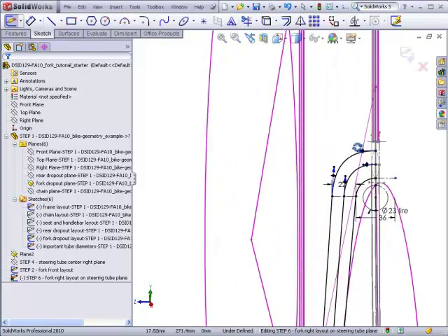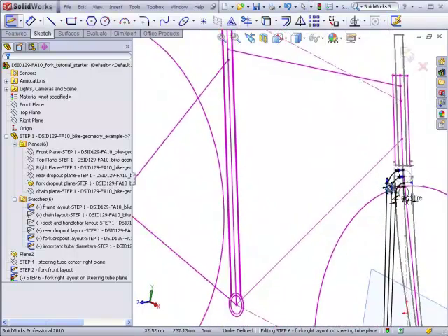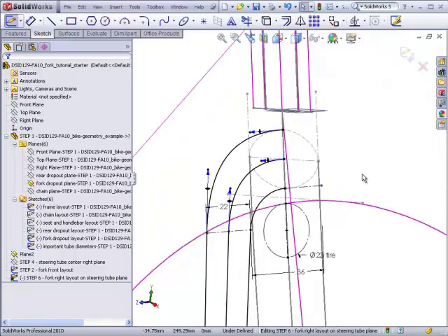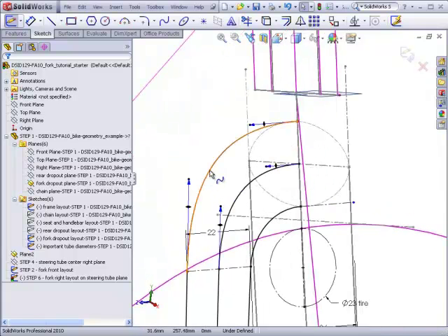And these have to be drawn in such a way that they meet up with the appropriate points in the front layout sketch. Here we see the outside curve meets this point of our oval cross section, the inside, this point, and the leading / trailing curve meets the center of the oval, which is in alignment with the trailing and leading points in the original front layout sketch. I've also made sure that these curves are horizontal right at the point where they meet the front plane.